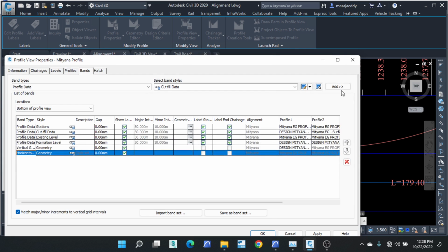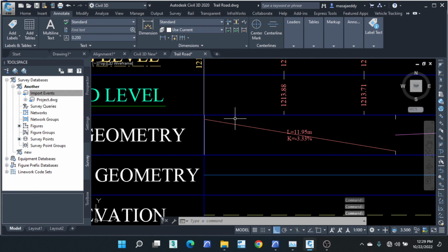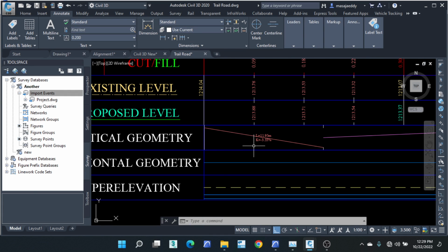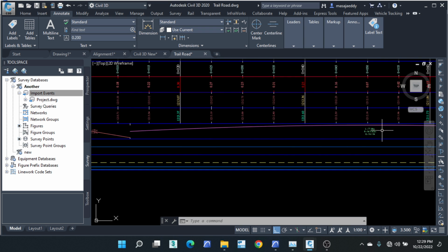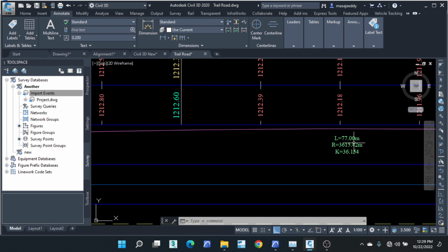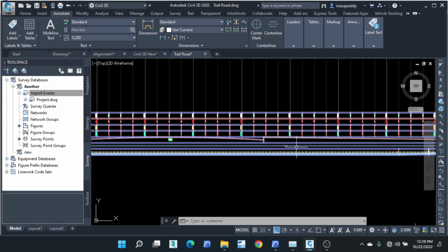What you need to be showing in the horizontal geometry, for vertical, we are looking at the distance of a line and its curve value. That's what we are looking out for on the vertical variables. We have the distance of the curve, the minimum curve radius, and the curve value. That's what we're going to be editing. Horizontal geometry, literally the same.